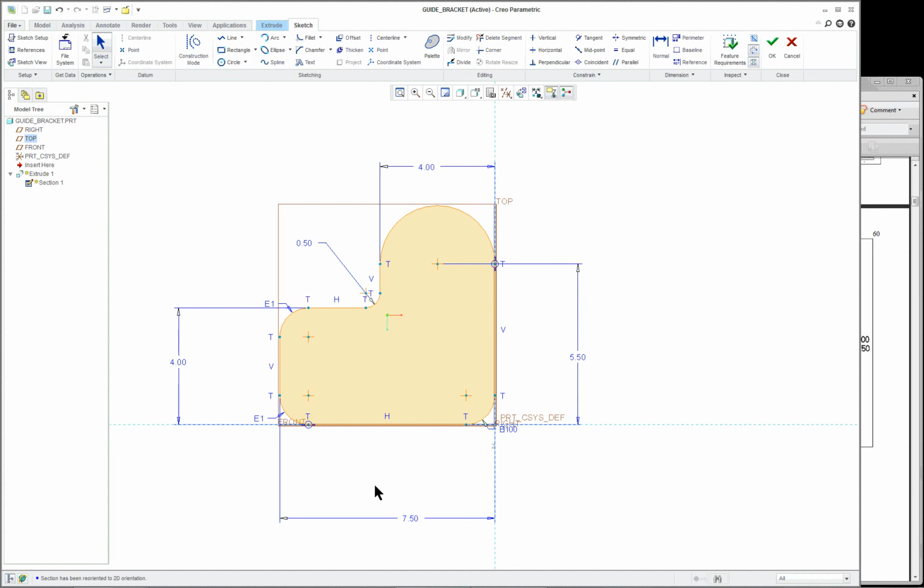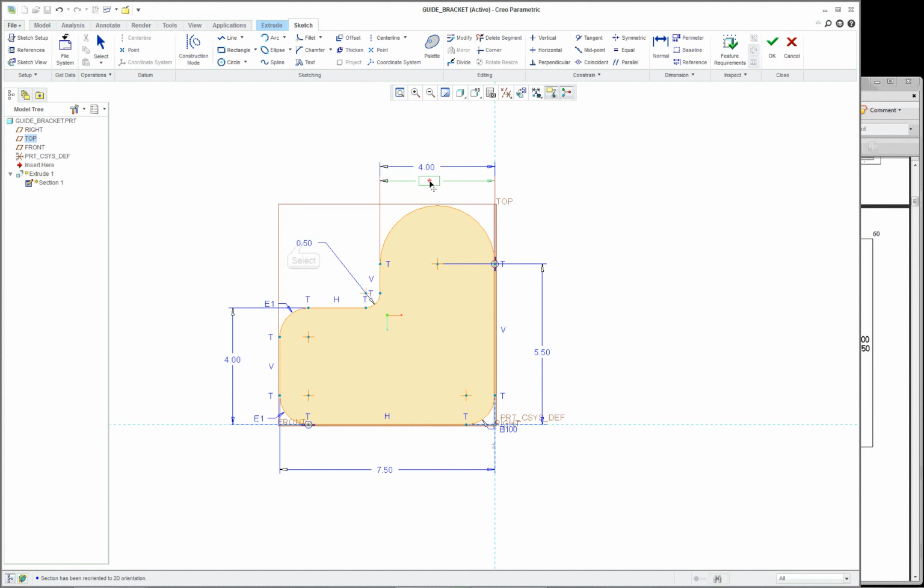Now normally you don't do that, but since these are large arcs, that's common practice to add them to the protrusion in this case. And this is our first one, first extrusion. Make sure you have your dimensions in here correctly. These are the only dimensions you're going to need. Nothing else. And normally what I do is when I'm doing my sketch, I actually position my dimensions like I would like to see them when I get to a drawing.